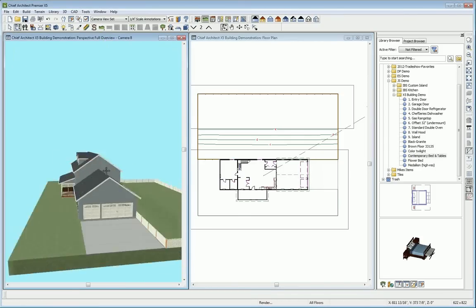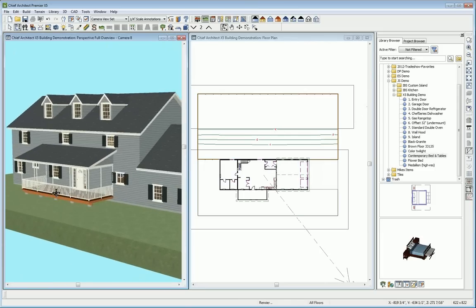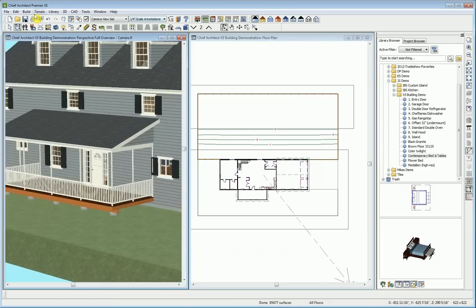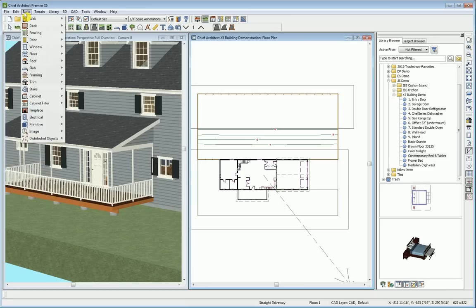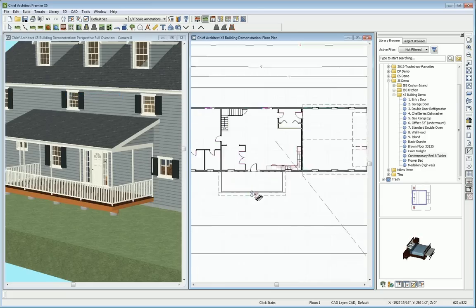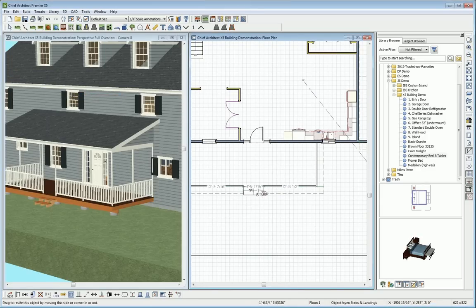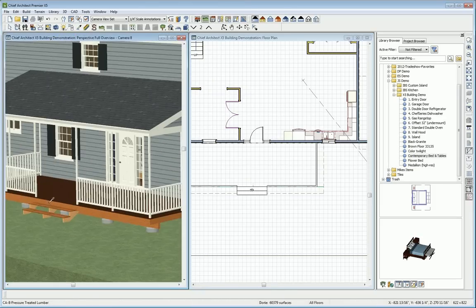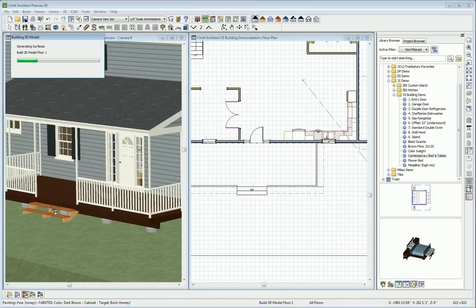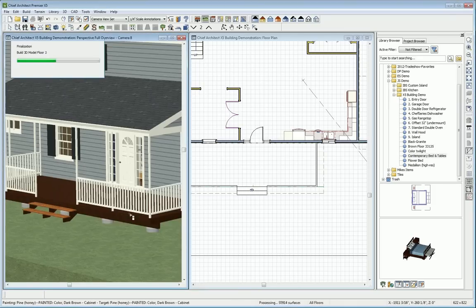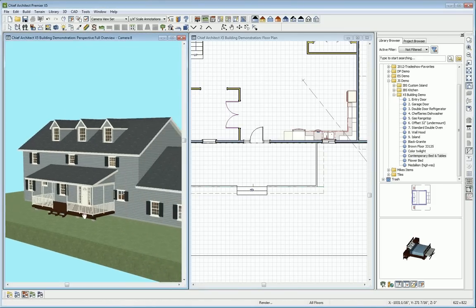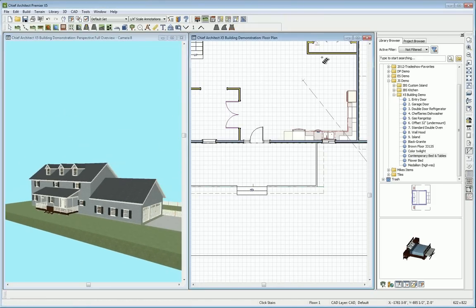And within our 3D view, we'll add some stairs going onto our deck. For this, I'm going to use our one-click stairs. So under the Build tool, I'll come down to our stairs and add our click stairs. Click right outside the deck railing, and you can see the stairs that were generated. We'll just make these a little bit larger. And you can always use your material eyedropper to match up the colors. Alright, so it's coming along pretty well.